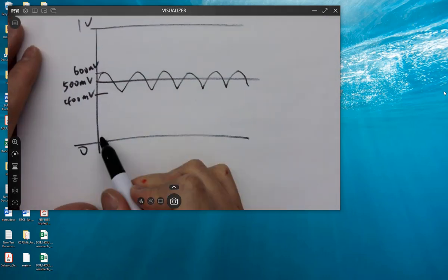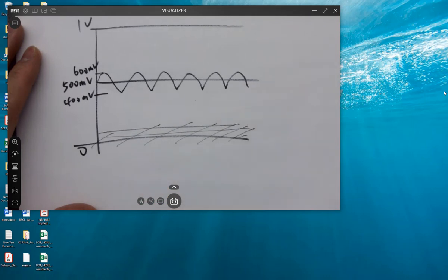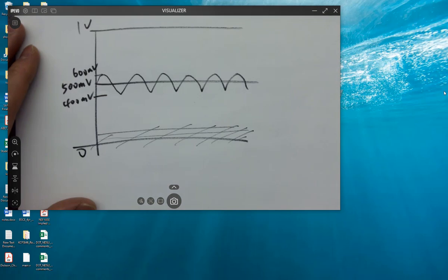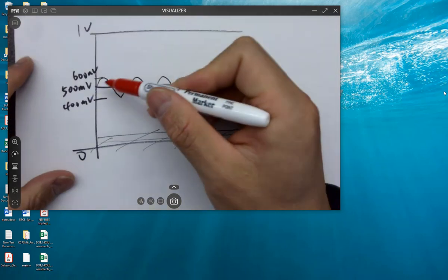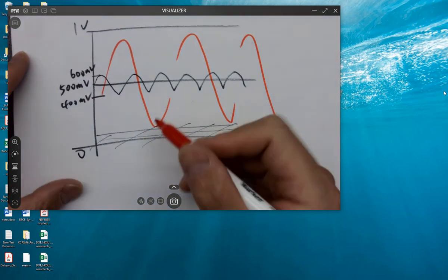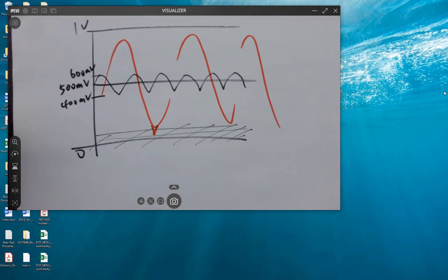So there's no low voltage. So this range is bad because the ADC cannot do it really well over here. So I just avoid it, right? But there might be some situations where you have to get a wide swing range. So the analog signal probably is gonna swing like this, right? And maybe there will be a chance this one enters that zone here, and eventually you're getting a lot of errors.